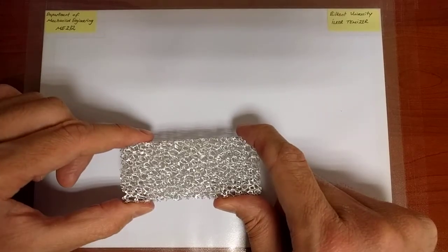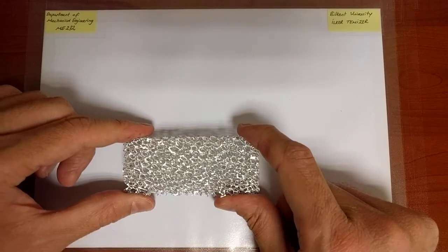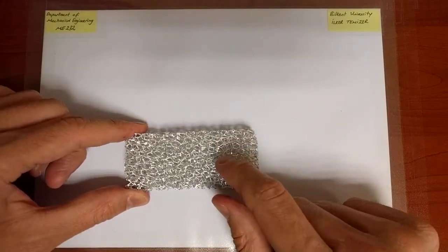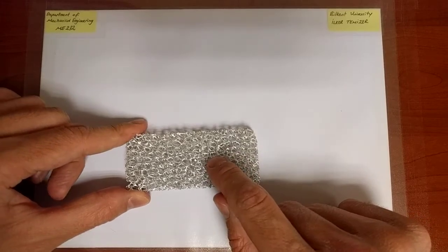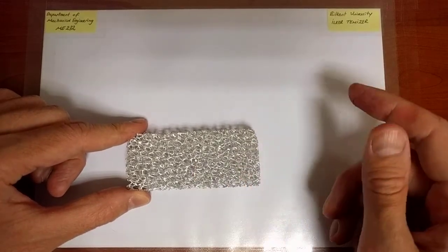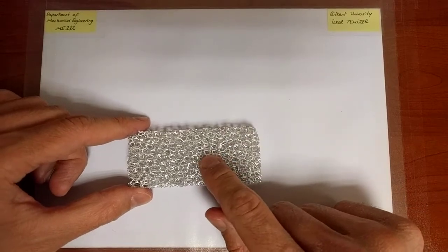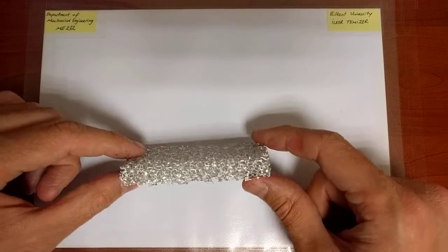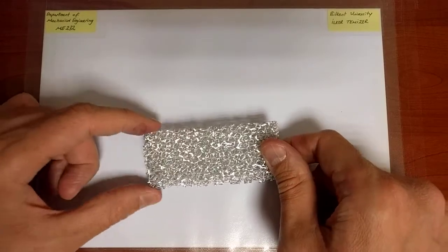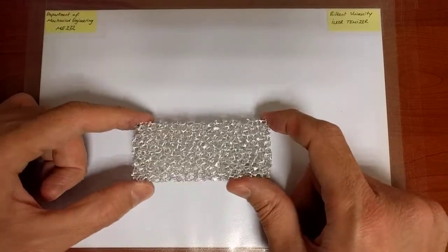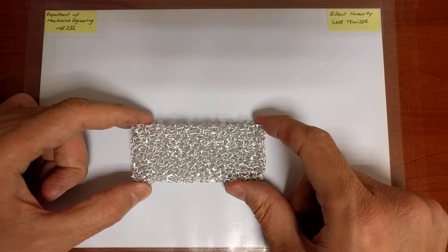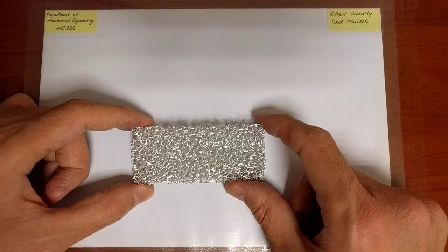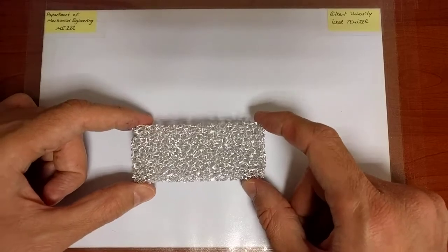This can be isotropic, but nevertheless the properties are different from the properties of aluminum because the solid part behaves like aluminum, but when I put so many voids, I sort of weaken the structure and end up with a different structure, a different mechanical behavior, which finds its own uses in, for instance, energy absorption, which could be mechanical like impact, or sound absorption, etc.